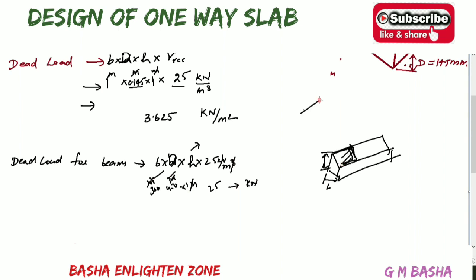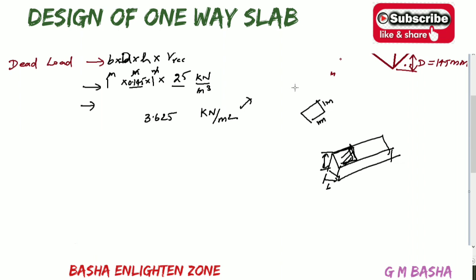But for slab, both sides 1 meter lengthwise and 1 meter widthwise. Therefore for slabs you are considering kilonewton per meter square. For beams we are considering just meter. Why? Because already we know the breadth and thickness, means depth, of that particular beam. So that is the difference we have to remember for calculating the dead load of the slab and dead load of the beam. So here the dead load of the slab will be 3.625 kilonewton per meter square. So you know the difference why here it is considered in terms of kilonewton per meter square, and for beams it is kilonewton per meter.